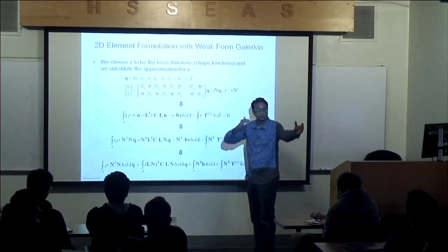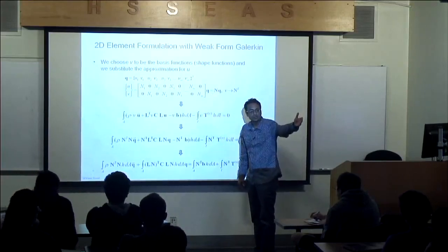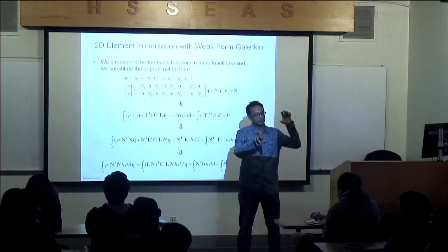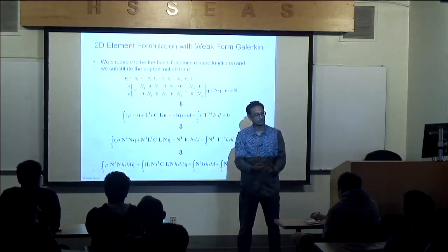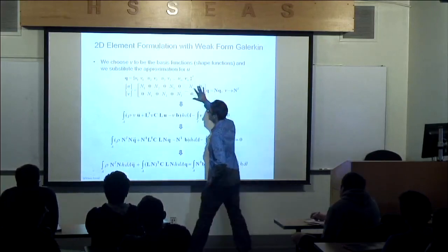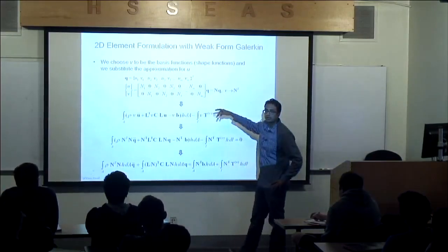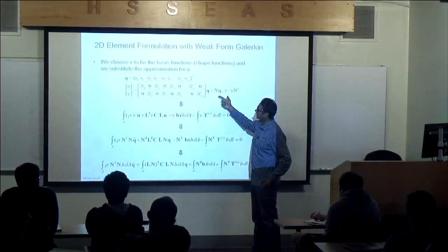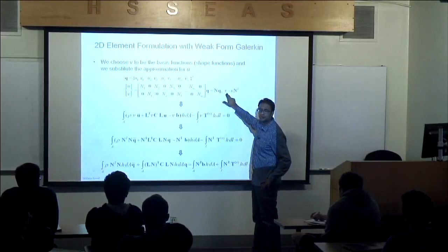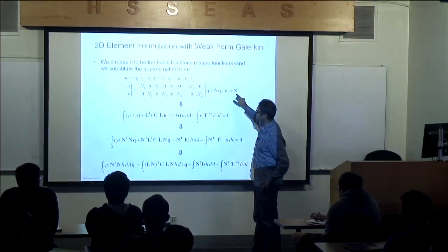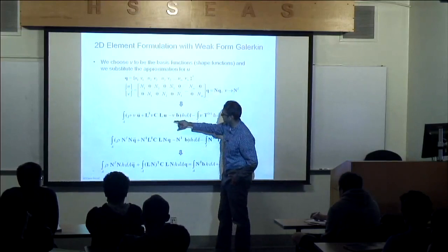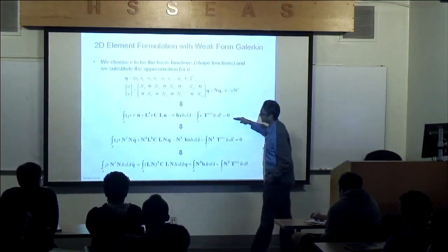In weak form Galerkin, what you really had, like if you go back to lecture number 5, wasn't the weak form Galerkin like unknown coefficients times basis functions? And then I'll plug that in, right? This is what we're doing here. I have basis functions times unknown coefficients, and that's what I'll plug into my weak form. And when I do that, I also have to select my basis function, my weight function, to be the basis functions. So I'll make it N transpose. So let me begin. So I did it here. So this is my weak form when I started.